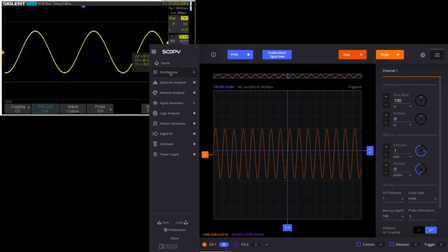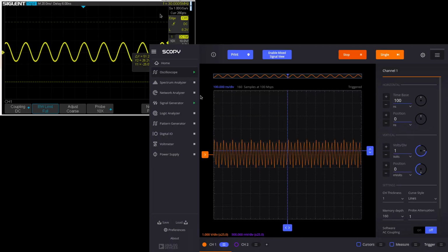Sine waves are relatively easy because they don't have any high frequency content above the base frequency of the sine wave. At 30 megahertz, the M2K display is pretty useless, and you wouldn't think that's a sine wave. The Siglent is still showing something that is somewhat like a sine wave, although greatly diminished in amplitude. The bottom line is that the M2K is doing a pretty good job of generating a sine wave at, say, 10 megahertz. Above that, I begin to get a little bit suspicious.